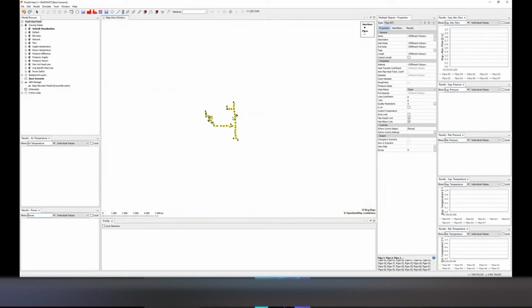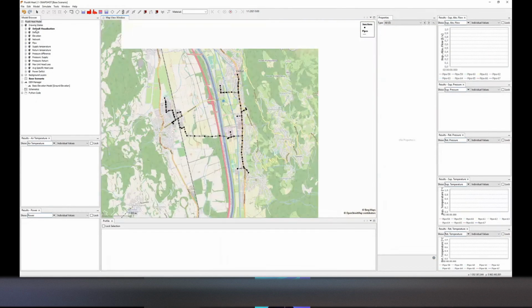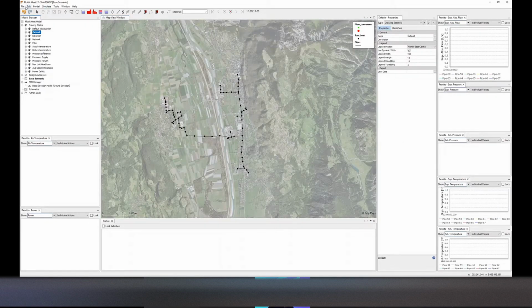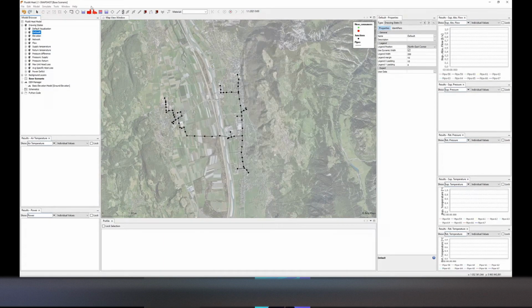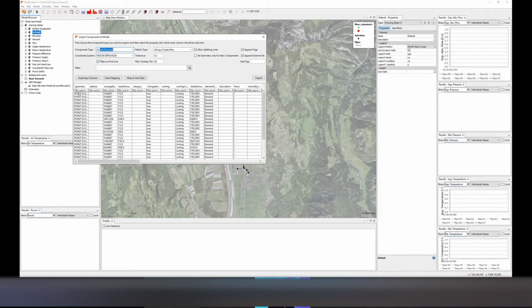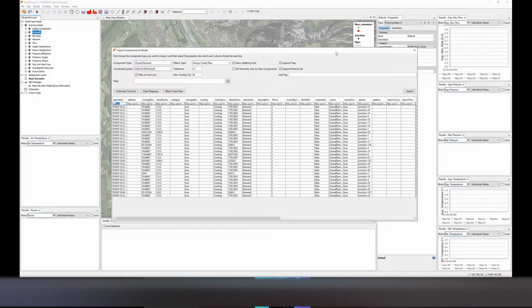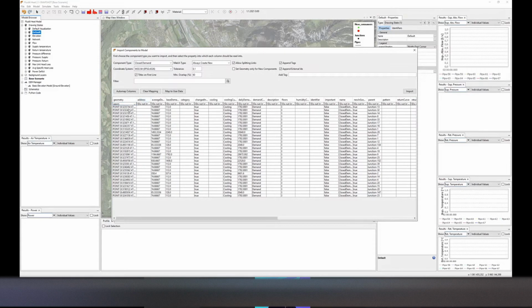in the capital Vaduz. And what I also want to be bringing in is some consumers that exist in the network there. So I will be bringing in some of these, and this would now be consumers. We can also bring them from Excel files and many different types of sources, but these ones already have geometry very nicely, X and Y coordinates. Then I will be giving them their base demand according to each, and a cooling curve and a demand curve, so that they will be behaving according to outside temperature.